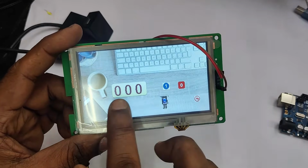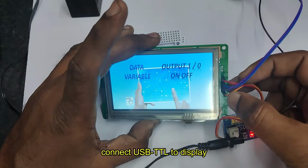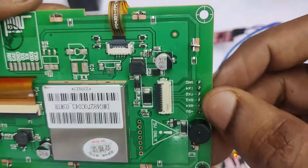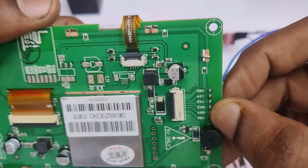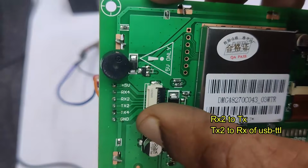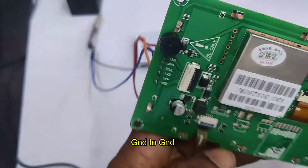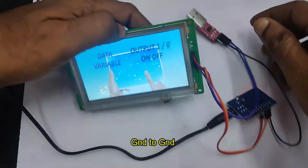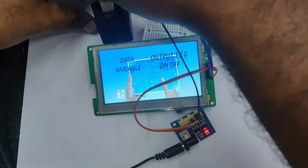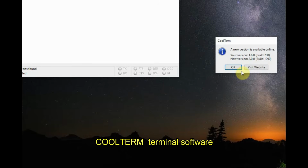Now let us connect the display to a USB to TTL device with the CP2102 to decode the hex code. For this we have to do the connections at the TTL connection, that is RX2 and TX2. We are not using TX4 and RX4, only RX2 and TX2 used. RX2 goes to TX of CP2102, TX2 goes to RX of CP2102, and ground to ground.